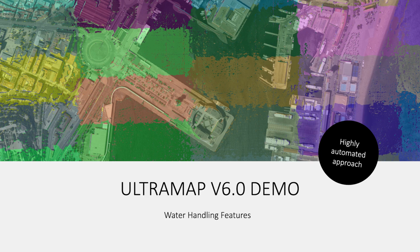And now with version 6 there's a new blending mask editor available, and this is first applied to water only. Seam lines on water bodies are blended to give the orthomosaic a more homogeneous look on water, and if needed that blending mask could also be applied to certain regions on land. So that's it for this first overview. Now I would like to switch over to the demo of UltraMap version 6.